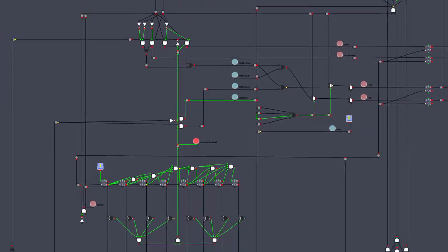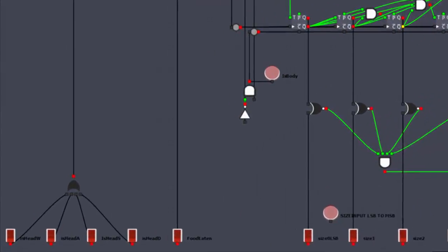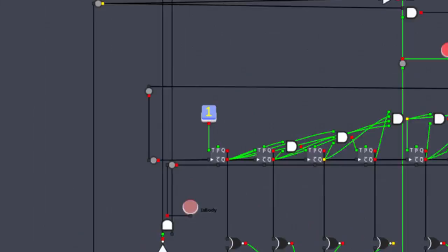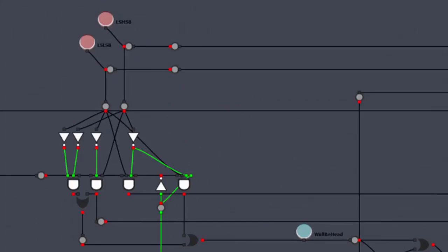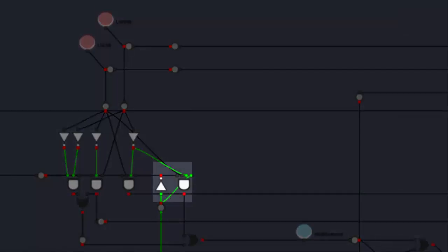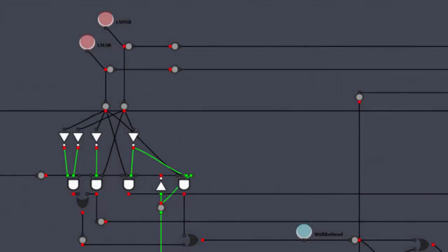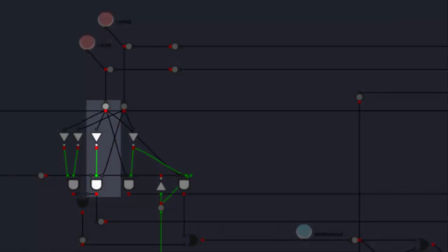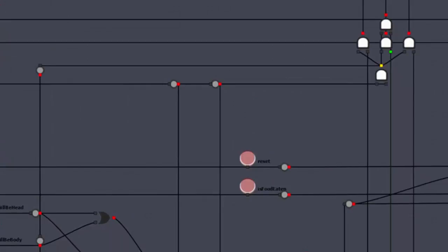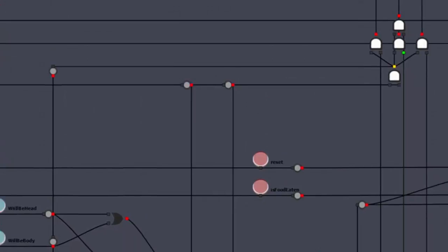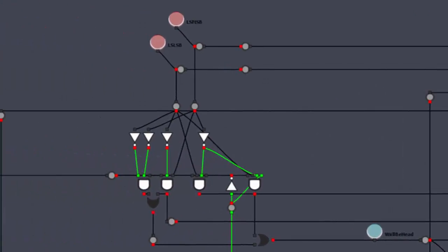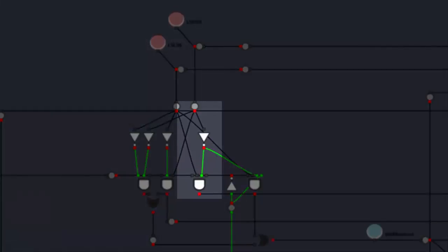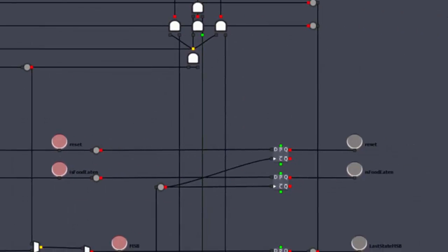For determining if a cell must be a head, the circuit checks if there is an incoming will-be head signal and the current state of the snake. If the cell is air or the body that is about to become air, then the cell should become a head. If a cell is food, then a food eaten signal should be sent to represent the head eating the food, and the cell should also become a head. If the cell is already a body or a wall, then a reset signal is sent.